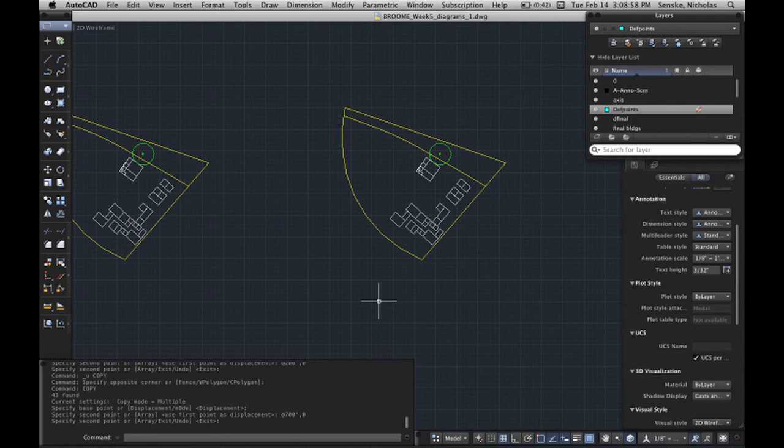Illustrator is just for line weights. Sparing line weights, right? Figure out how many, maybe you have 3 or 4. Maybe you have 1 red line and 3 black, and that's all you use for the whole thing. What's the hierarchy of those drawings? The idea of any set of architectural drawings, if you have a layout, is that they all came from the same set of pens. You have a bunch of Microns on your desk, and if I'm Rachel or whatever, I have 4 pens. I did all the drawings in 4 pens, okay? On the computer, it's easy to make up a bunch of different weights.